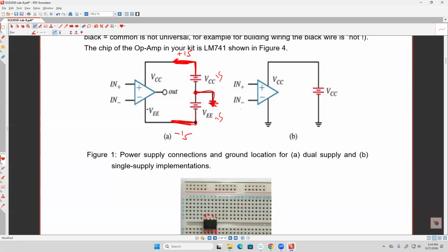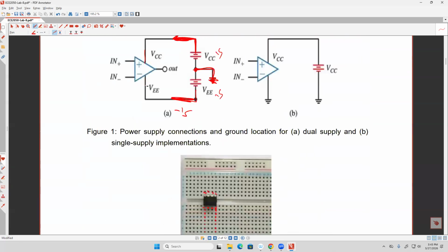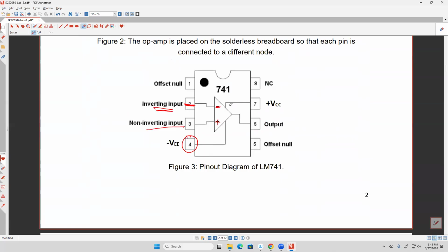So now you need two channels from the power supply to connect them as shown here. Okay. And then positive 15 has to go to this one. Which pin is that? Let's see. Which pin is that here? Sorry. Yeah, here, this is pin number 7. Okay. So for example, if you select 15 and this is a negative 15.